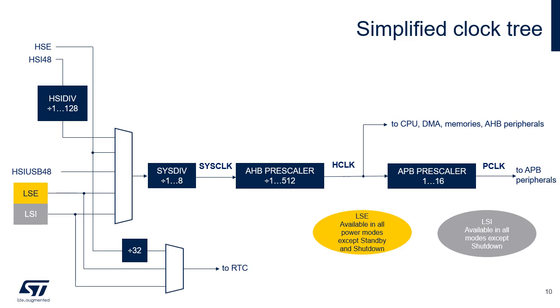The LSE can remain enabled in all low-power modes except shutdown. The LSI can remain enabled in all modes except shutdown and standby. Each oscillator can be switched on or off independently when it is not used to optimize power consumption.